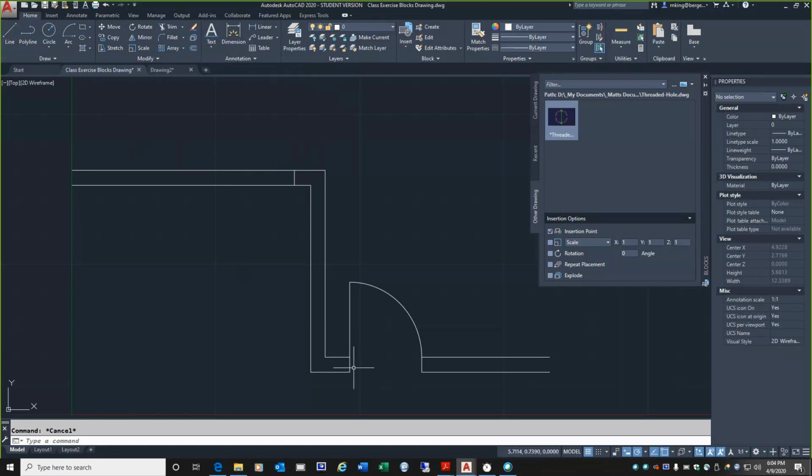And now because we know our opening's 1 1/4, let's offset this line over 1 1/4. Okay? So I'm going to go to offset, and I'm going to type in 1.25, enter. Clicking this line, moving to the left, and clicking, and then enter. Okay? So there is my door opening. Let's go the extra mile and actually trim that. So I'm going to trim, enter, and click.